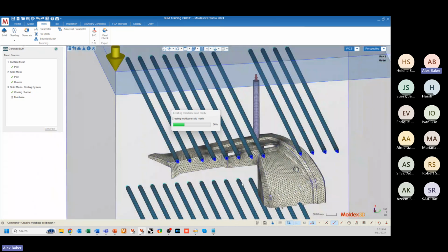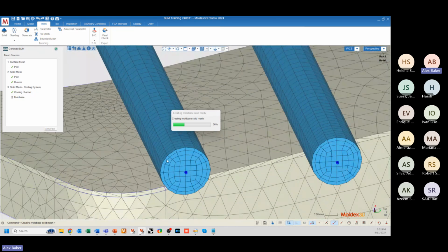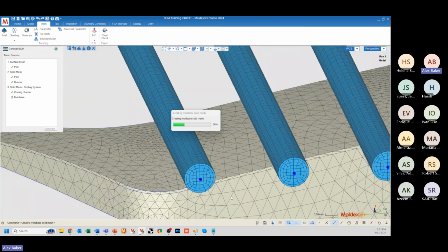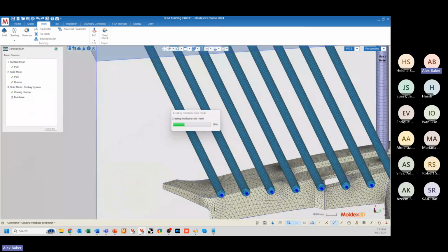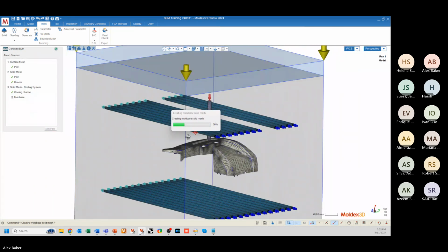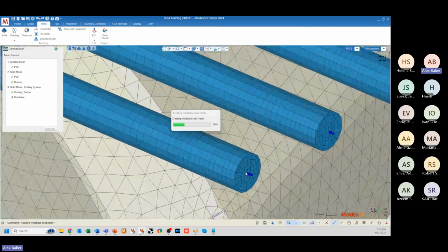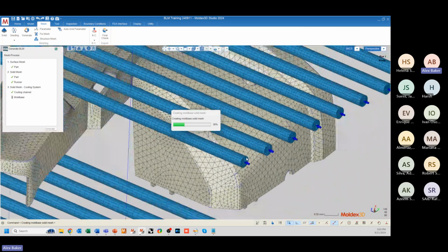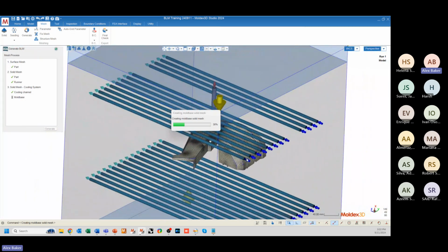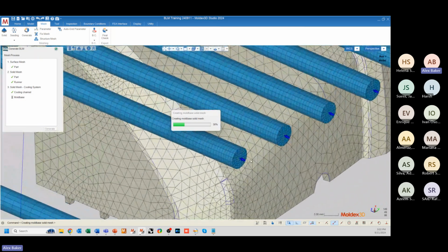And the same thing goes with our cooling channels. You can see that two-dimensional template extruded all the way along our cooling channels. A very perfect array, and the highest quality type of mesh that can be created in simulation at the current moment are these hexahedral elements.